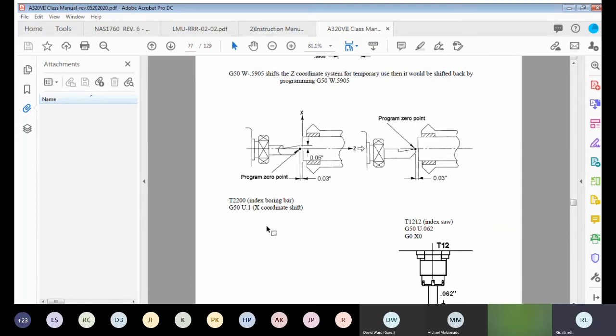We had a comment that people don't normally put them in geometry, let's say. So, is there a right way or a wrong way? Well, that debate can go on forever because it's really user preference. I see probably the vast majority of people doing it this way, but some people like to put the values in the preparation page. My argument for that is if you put the G50 shift in the program, it travels with the program forever. It's always in there. Geometry you have to put in, and it could be an issue a little bit.